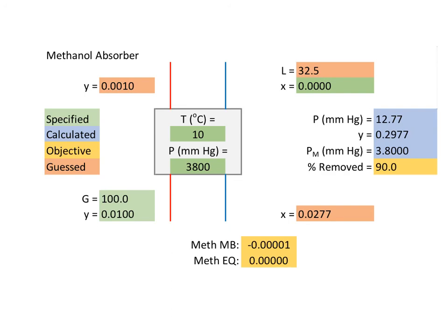One of the major assumptions we made in this solution was that the air and the water do not transfer phases. Well, air is not very soluble, so I wouldn't expect a lot of it to wind up in the liquid, but water can definitely evaporate into the gas phase. There's not going to be that much here at 10 degrees C, but if you operate, for instance, a stripper, which operates at a higher temperature, you will get a significant amount of water going into the gas phase.